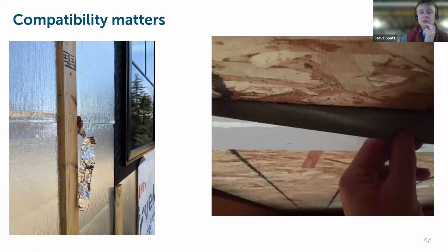So the point I'm making here is to just be curious about what your options are and to dig into it a bit and consider the compatibility for outcome as to why you choose one tape versus another for the type of material that you're bonding it to. And also make sure that the materials that you're looking at here are compatible. If your tape doesn't stick to the substrate, stop using it and find a different option.